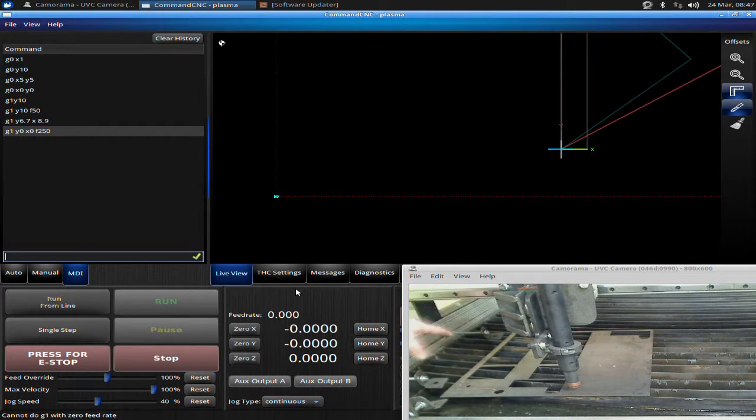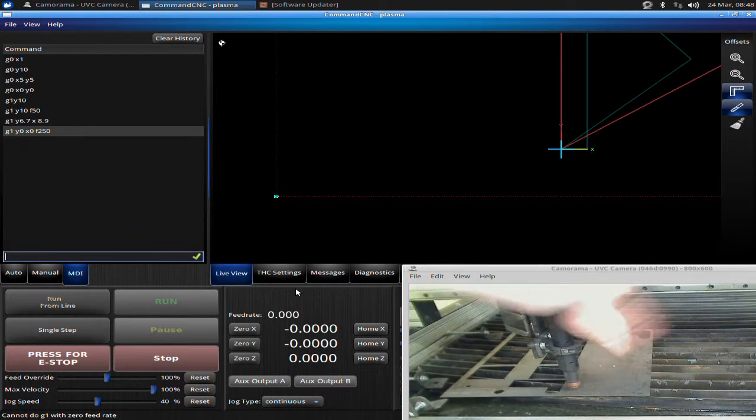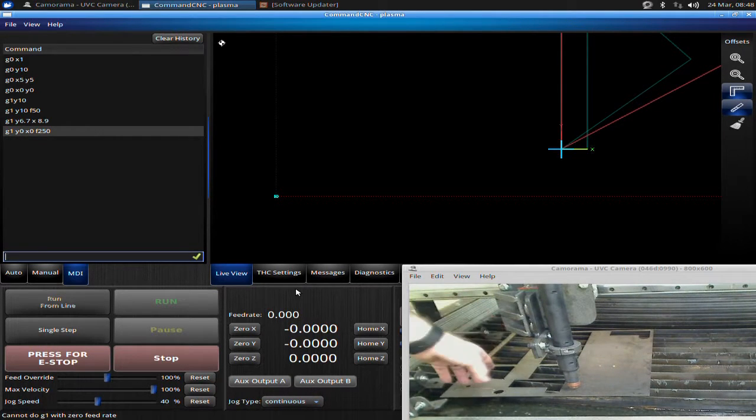And basically what you do is you set it up, your jig's in a set position off the 0, the machine 0, so that you can know exactly where your part is. And a lot of people do this when they want to cut tubing. They'll set up a jig so they can lay their tubing down and then have multiple tubes laid out, so that the tubes are a known distance apart from each other. Okay, so this is one way.